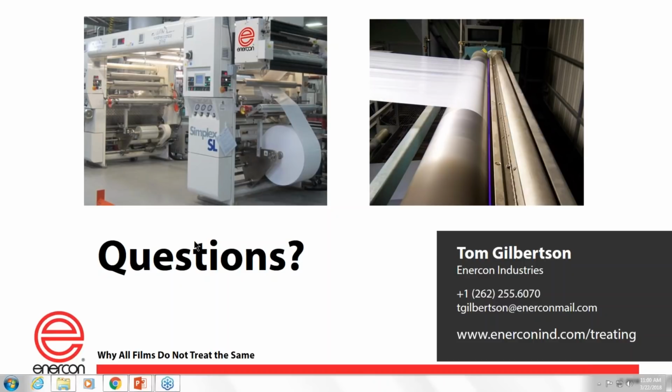The one thing those systems can't do is if you had an application where you require lanes of treatment, meaning I treat 6 inches, I skip 2 inches, I treat 6 inches, and so forth. That system can't do that. Then you have to look at a different type of treater. But the difference really is these bare roll systems versus a hybrid system. Hybrid systems, ceramic roll systems, give you much more flexibility and really are the standard in the converting business.